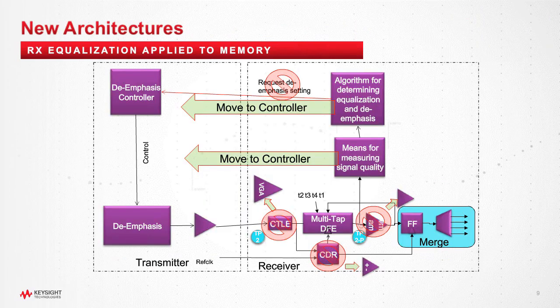In PCI-Express, the receiver is actually quite intelligent. And it is in control of the training sequence that is used to basically figure out what the equalization factors need to be, and whether some additional pre-emphasis or de-emphasis is needed by the transmitter.